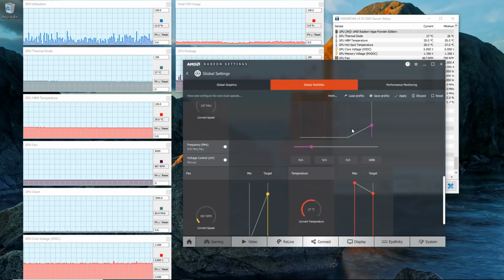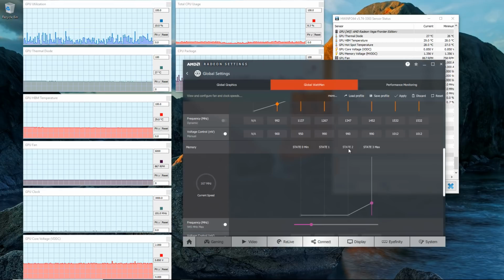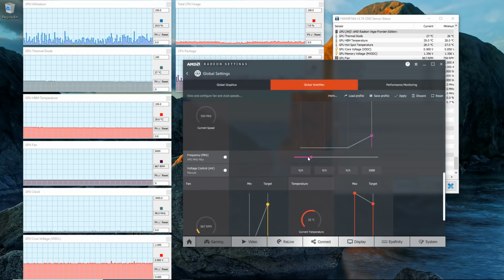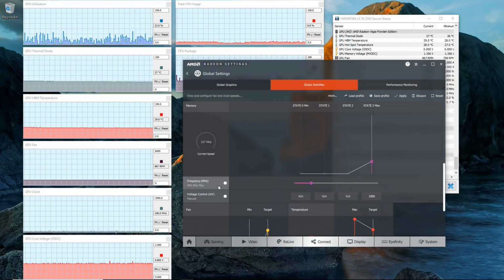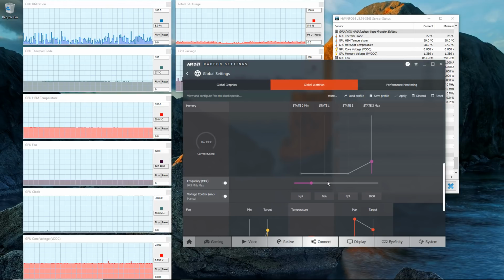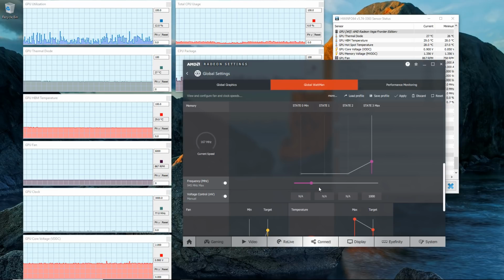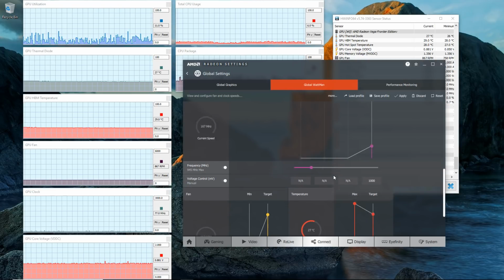You can kind of go back and forth on it, and you could come up with an iterative process, but it is a lot of work. So I would probably just increase this slowly until I find a point where instability is introduced, and then you just back it down a hair just to make sure you're not running into that problem during the course of normal operations.